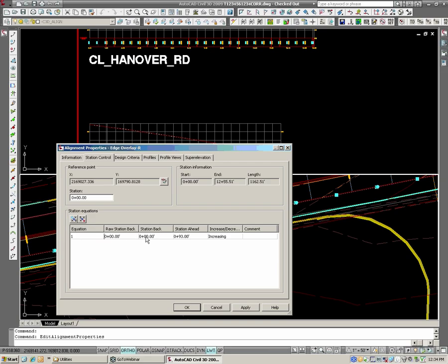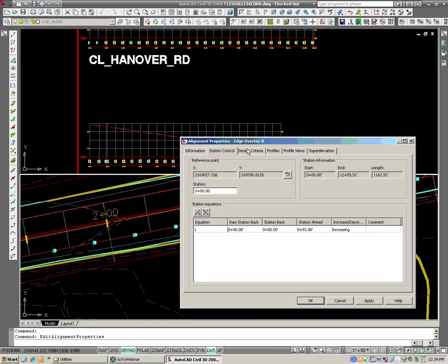so that station 0+00 on my right overlay alignment is equal to station 93. So at station 93, it's going to reset and start at 0+00, which will, I had to do some math and look at the alignment, which will actually line up my stations all the way down. Now, since they vary, they become off as you go a little bit, very little, but it does line you up pretty good for making all your adjustments.